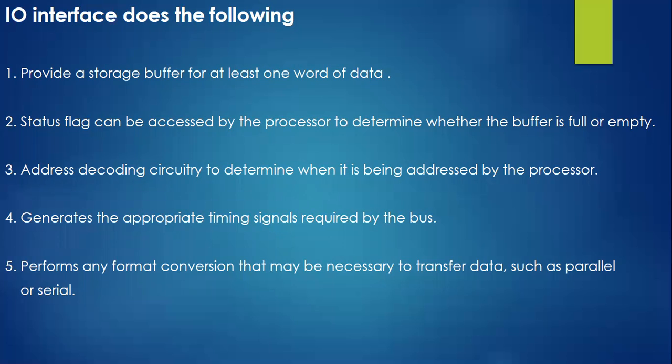Here the interface circuit consists of one more module. We call it the address module or address decoding module, which allows the device to decode the referred address. If the decoded result matches the address of the device, then the control signals available in the controller make the device start behaving accordingly. So this is also one of the main roles played by the interface circuit.